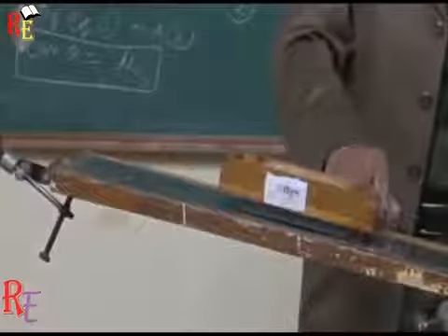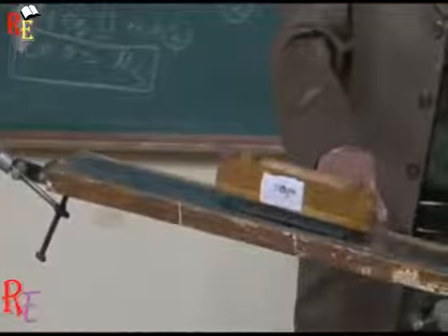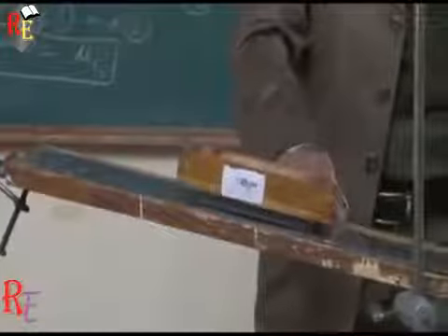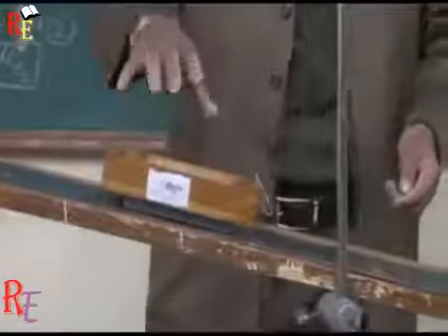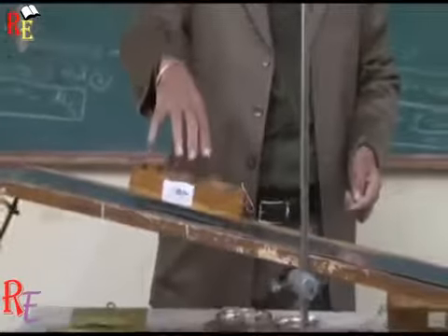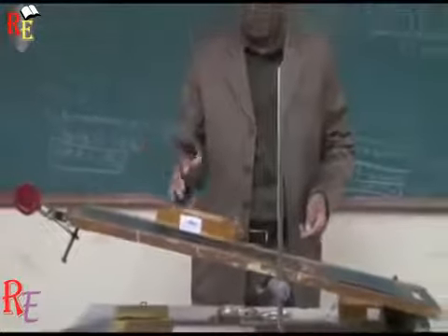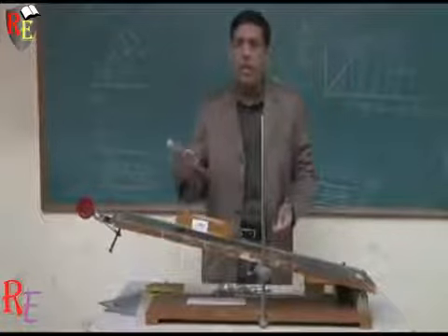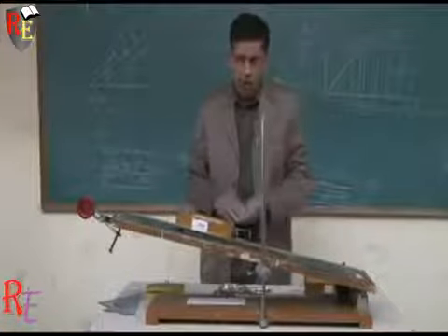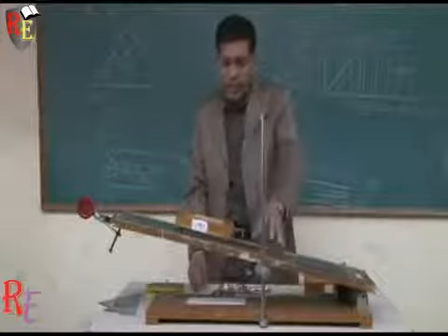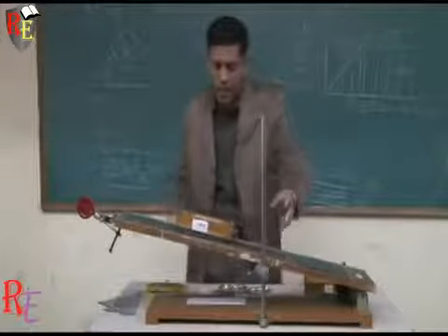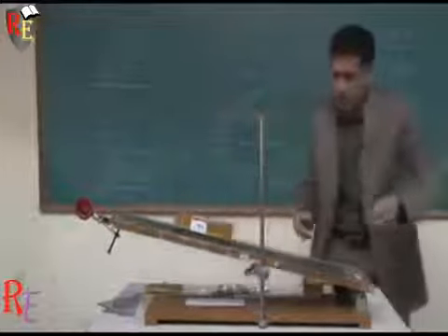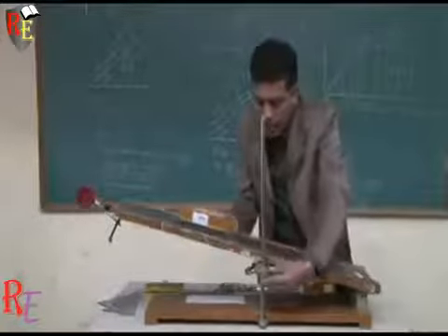Now I will gently tap this incline, and I would see whether this block is moving or not. This block is not moving. It means the net force acting on this block is equal to 0, so the force of friction does not have the maximum value. Now I would keep repeating this while changing the angle of incline. I change the angle of incline.